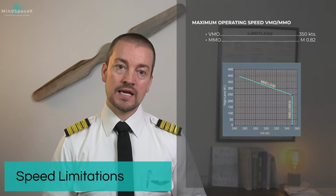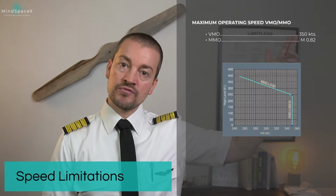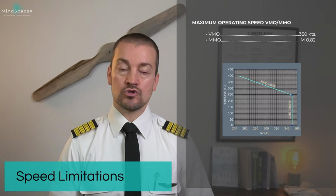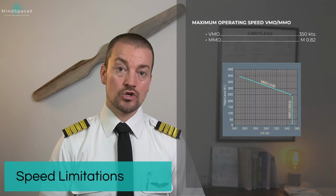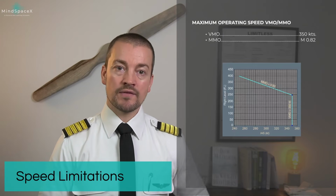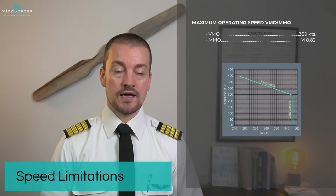Maximum operating speed for the aircraft is VMO or MMO, 350 knots for VMO and Mach 0.82 for MMO. The changeover from VMO to MMO and vice versa is automatic in this aircraft, and it happens at 25,000 feet, as you can see here.